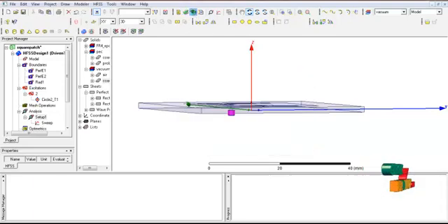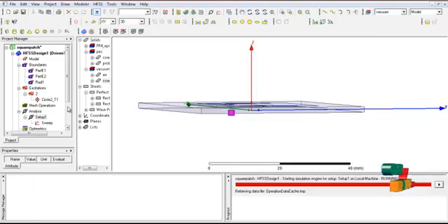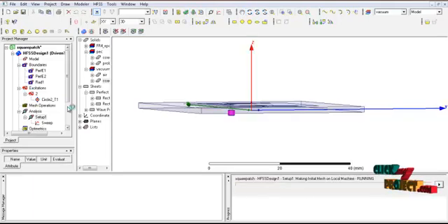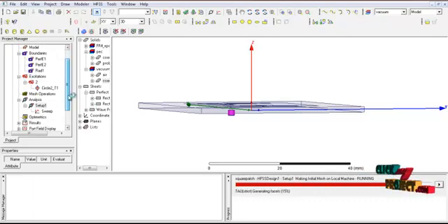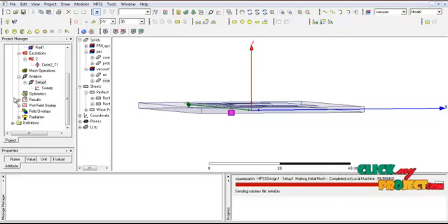So this is the run. To run the process, we click this button and then run. It takes some time to display. Finally we calculate the overall results like return loss, VSWR, radiation pattern, and the 2D and 3D of the process.